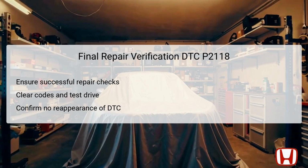Following this, a test drive should be undertaken to ensure that the vehicle operates smoothly without triggering any fault codes. During this trial, the technician should monitor the vehicle's throttle response closely. The ultimate goal is to confirm that DTC P2118 does not reappear, reflecting successful resolution of the underlying issue.